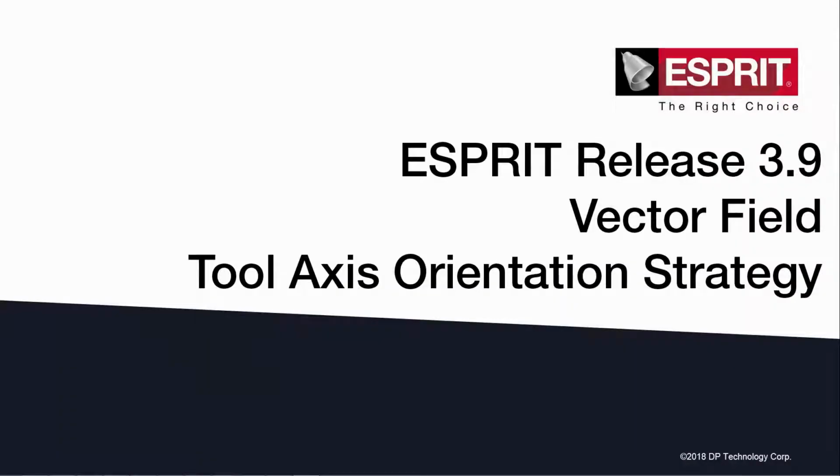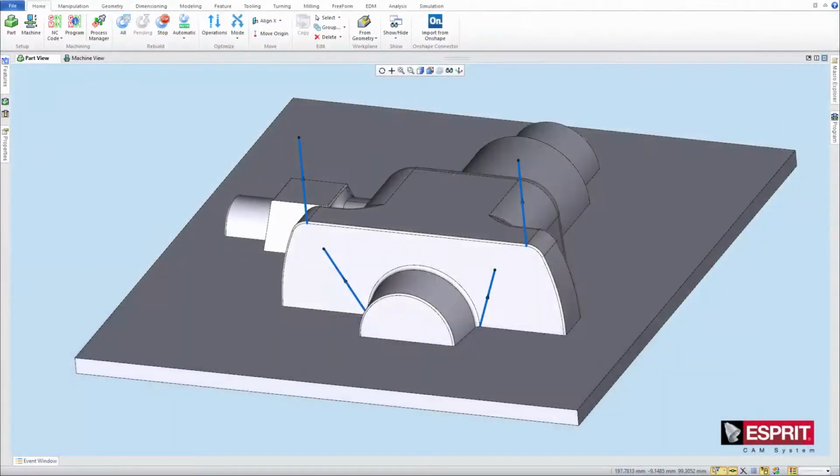Welcome. This video will describe the new vector field tool axis orientation strategies for composite milling, now available in ESPRIT Release 3.9. There are two new axis orientation strategies for composite milling, vector field and vector field on drive surface. Both strategies use open chains to define the vector field, but each uses a different vector domain.